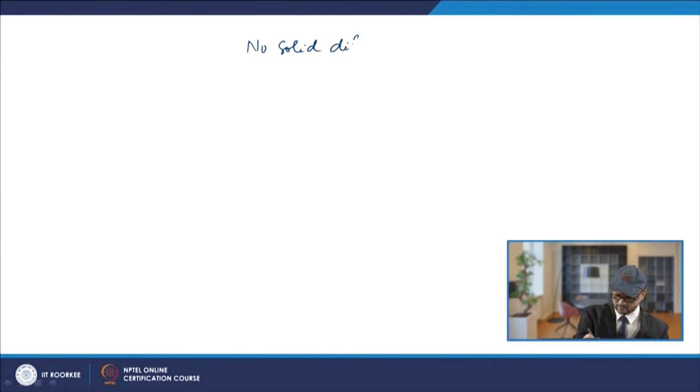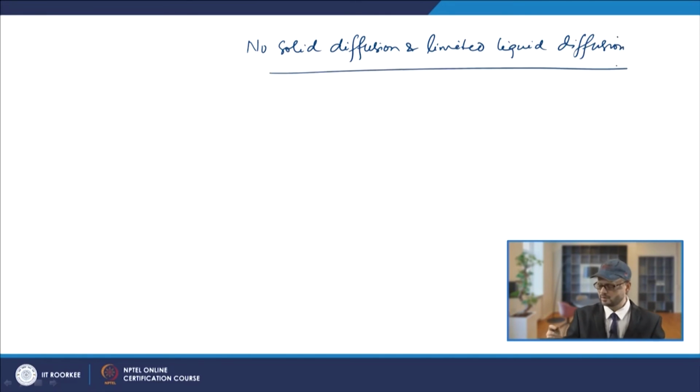There is another case where you will have no solid diffusion, and you have limited liquid diffusion. Now, in such cases what is happening is that you will have solute build up at the interface, because in this case you have only limited liquid diffusion.